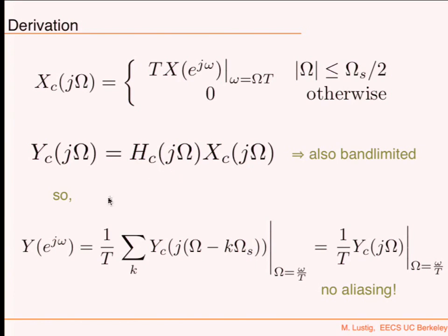theoretically. Okay, so now the digital signal that comes out is really a replication of this. Right? When I sample, I replicate. Right? So whatever is between minus Ω_s/2 to Ω_s/2 should be replicated. Okay?